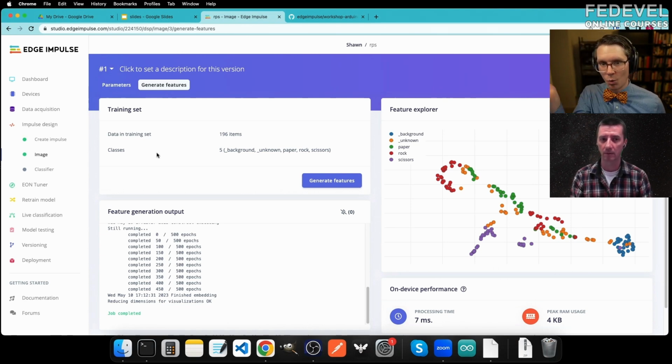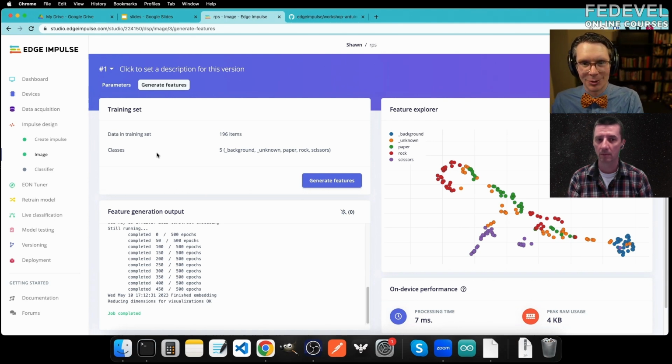Most of the time, even like your wand thing, it's usually spectral, especially for vibration analysis, which makes a lot more sense. But it does mean you have to do an FFT or multiple FFTs on top of your actual inference, so more computational power is required. That's where a lot of the DSP comes into play: you're doing DSP stuff on top of doing machine learning. But there are algorithms like recurrent neural networks that work better with time series. I don't know how well they work on keyword spotting. If somebody else has played with them, they could say something in the comments. RNNs and LSTMs, the long short-term memories, are a form of recurrent neural networks. Those supposedly work much better with time series. I just don't know how well they apply to keyword spotting, doing audio data.